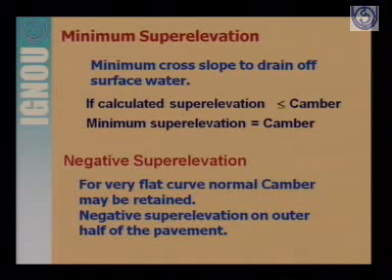In some cases there may be negative super elevation, where for very flat curves the normal camber may be retained. In such a condition, the negative super elevation will be on the outer half of the pavement.